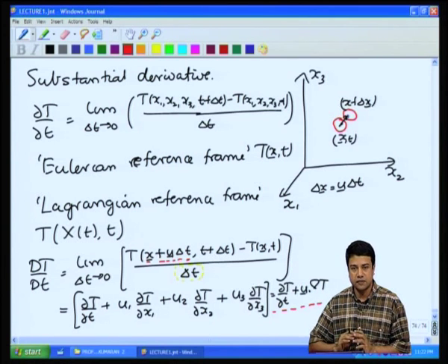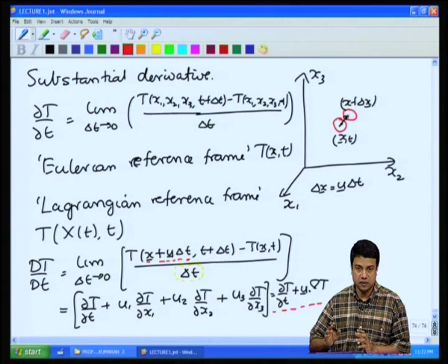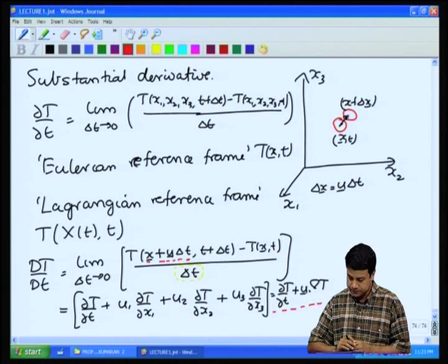It is in a Lagrangian reference frame, and it recognizes the fact that as the fluid moves, the fluid element occupies a new location after an instant of time in comparison to the original location, and you are taking the derivative on that moving volume element of fluid.